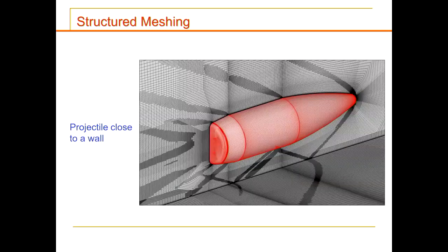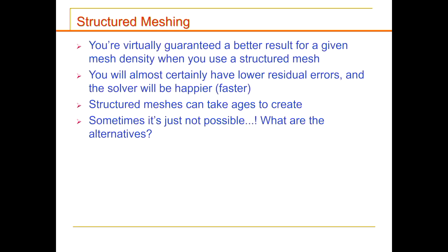So basically, this is another example of structured meshing. Again, it's more rectangular type, for a projectile. So that's a bullet, okay? Again, the same principle applies where you have mesh around the projectile itself to resolve the boundary layer, and also very fine mesh at the back of the projectile to predict the shock waves, okay? Right? So why is this structured meshing important?